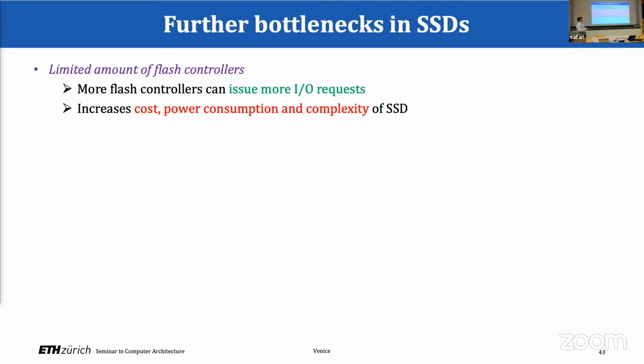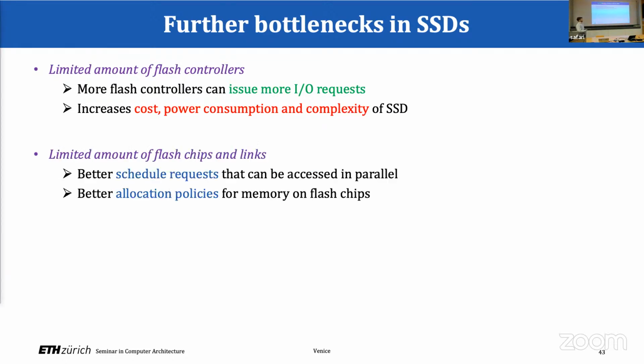Like you said, more flash controllers can issue more IO requests, but there's obviously a cost overhead, more power consumption, and it also increases the overall complexity of the whole SSD. So certainly an interesting research point, but it still has some disadvantages.